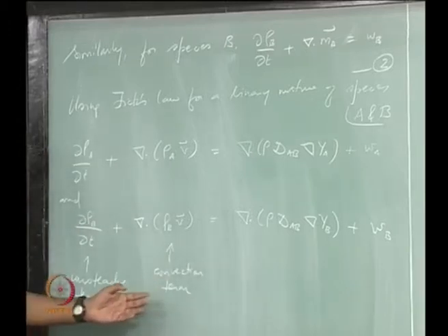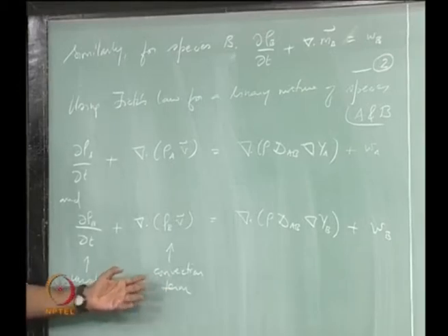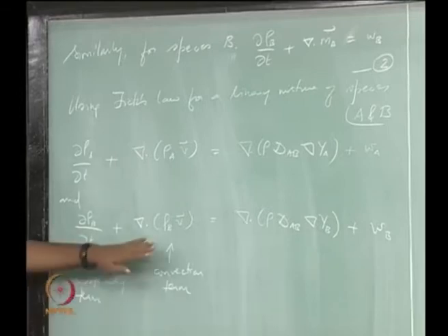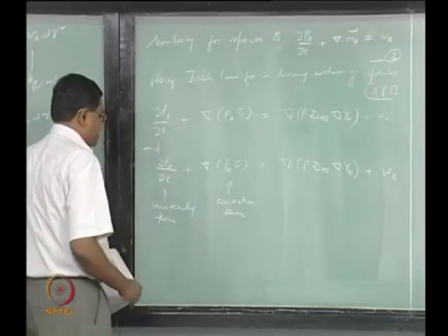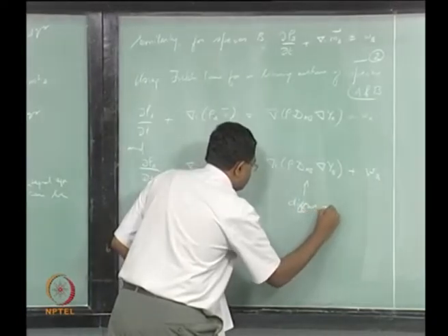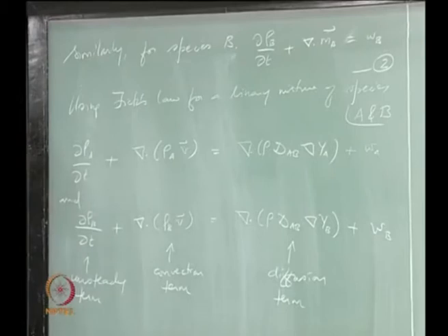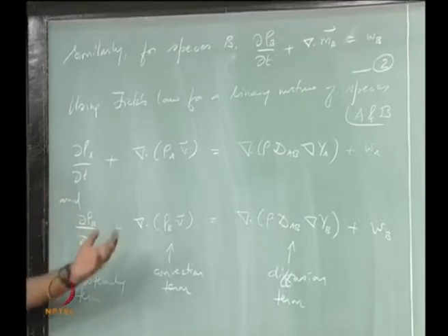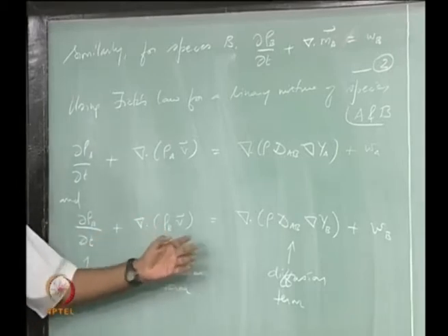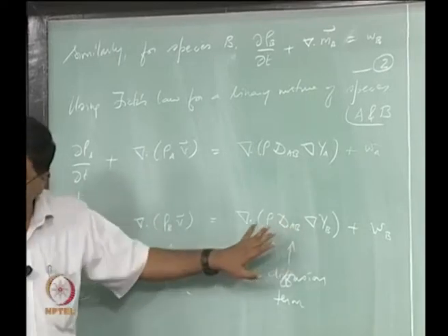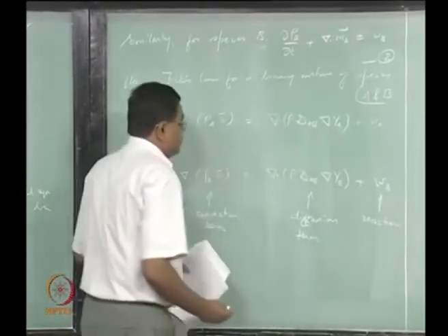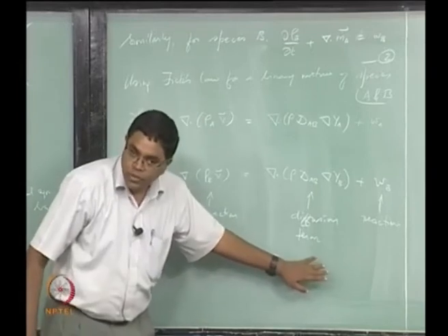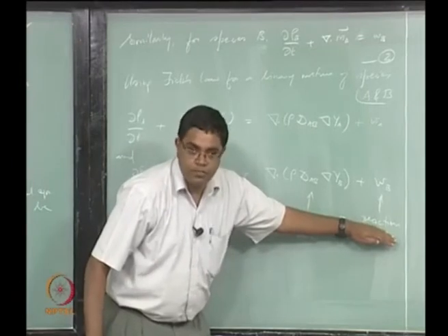Heat transfer people might use convection for natural convection, but aerospace people are used to forced convection most of the time, and they might call this advection. We are convective people, so we convect all the time, therefore we just call this convection, and this is the diffusion term. If you want to generalize most conservation equations, you would have an unsteady term. For example, in momentum conservation, you may have an unsteady momentum term and a momentum convection term. This would be diffusion, which would be a viscous effect, and then this is the reaction term in our case. But in general, this diffusion term could be referred to as a transport term, and the reaction term could be referred to as a source term.